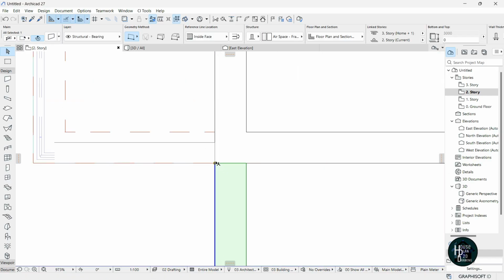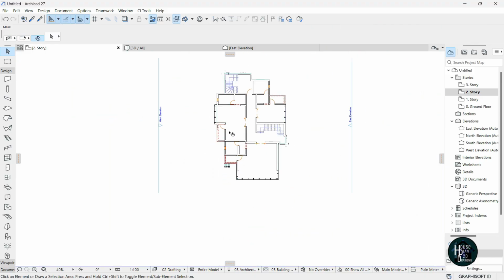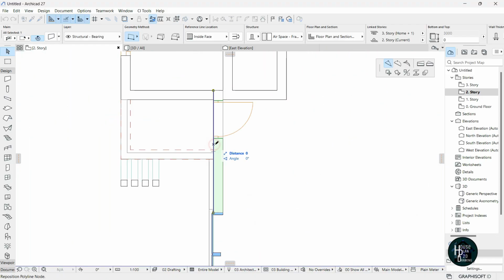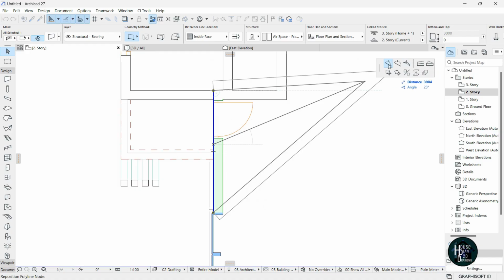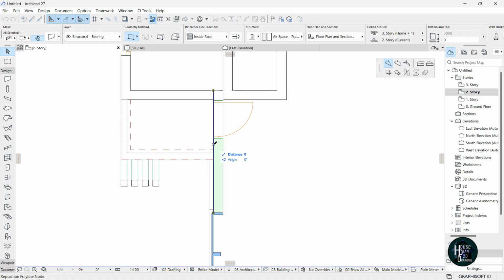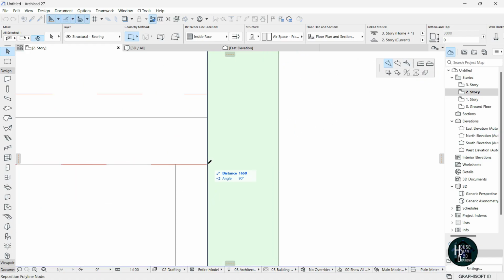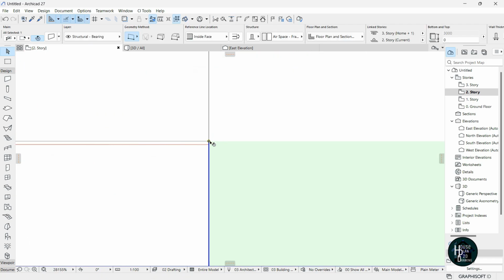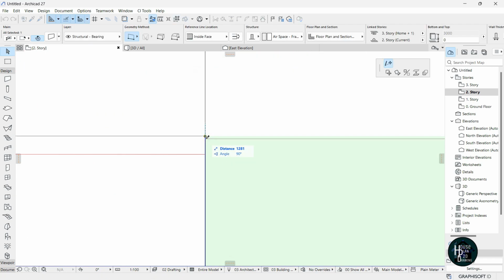Okay, so just a little bit so it doesn't spoil the design. So come to this other side also, click this, click it again, make sure you're selecting this insert new node and just hold on shift on your keyboard, then select this edge here. Okay, now click this again, since it's already split away from the surface, click this and just give a small gap.